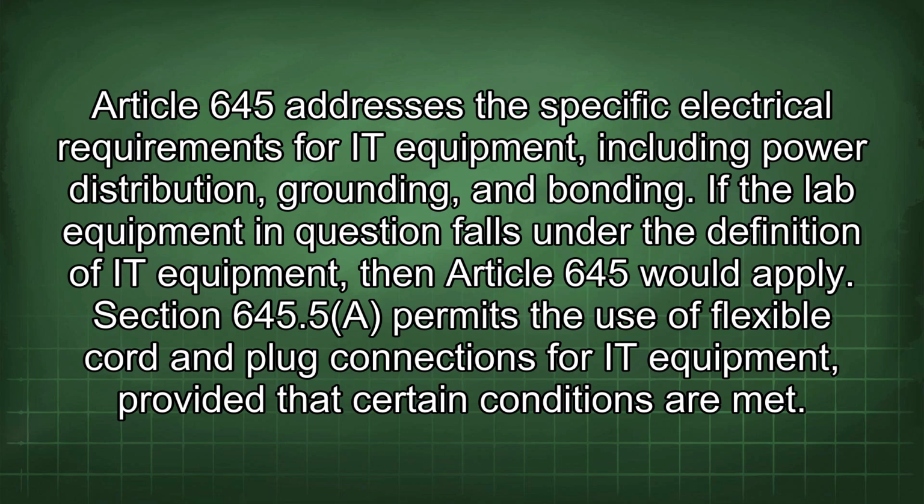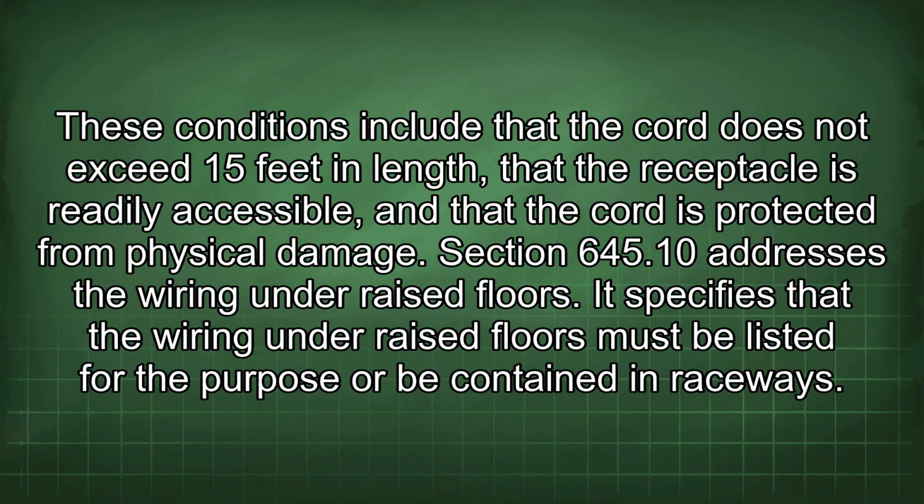Section 645.5 permits the use of flexible cord and plug connections for IT equipment, provided that certain conditions are met. These conditions include that the cord does not exceed 15 feet in length, that the receptacle is readily accessible, and that the cord is protected from physical damage.